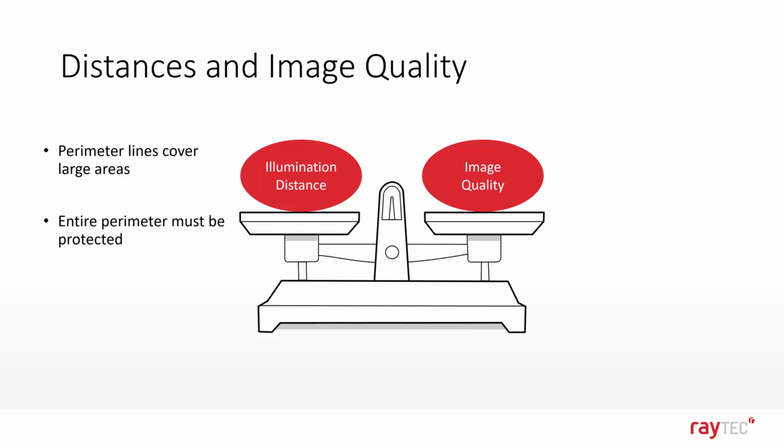So as I mentioned, you've got to cover every area. So when lighting is specified, we're normally going to recommend that the light goes further than the distance between the cameras. So if you're using 50 meters between cameras, we're going to specify 60, 70 meters. That also covers the area below the camera, so there are no dead areas, if you like.